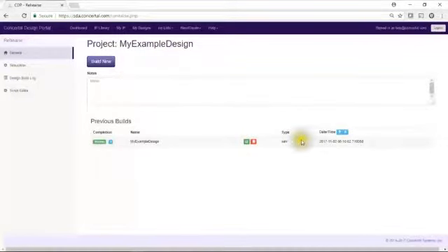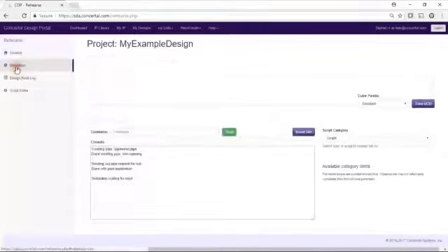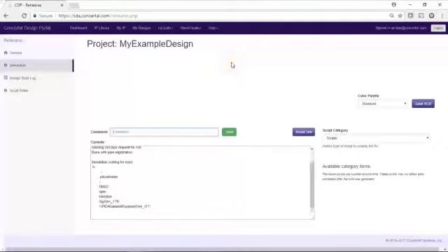Rehearse allows multiple builds for different versions of a design to be readily available. Compiled simulation builds with any embedded simulation scripts are kept on the server, and they can be picked up by others, providing a collaborative simulation environment for access by any stakeholders in a design. For now, we'll select the green button to load the compilation into the simulation engine, select simulation, and we're now actively simulating this design. The Tcl-based console runs with any standard web browser without installing any software. And it allows us to manually interact with the simulation engine or run simulation scripts.